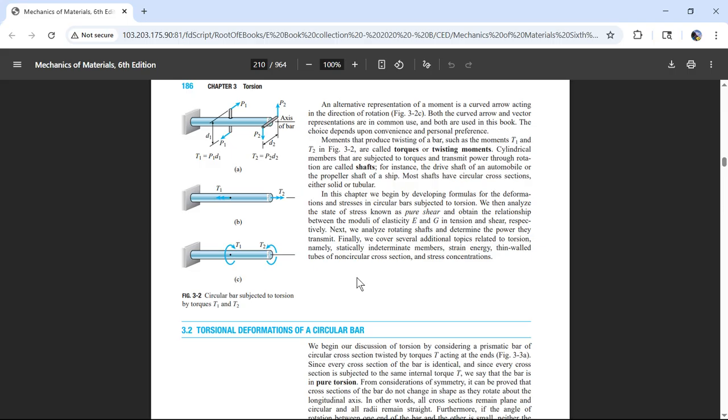And let's say that tank is 10 meters long. If you have a 1 meter bar of steel, this is a good number to know: for steel, it's going to change by 0.002, or just remember 0.2%. How do we use that number? If I have a meter bar of steel, that's going to be 1,000 millimeters.